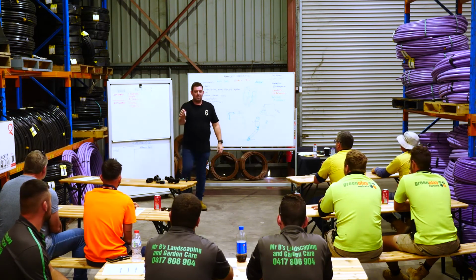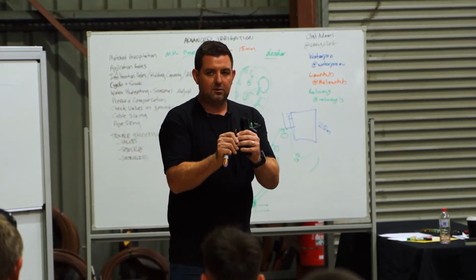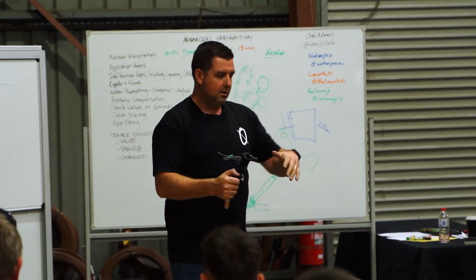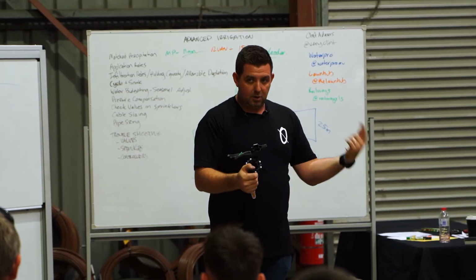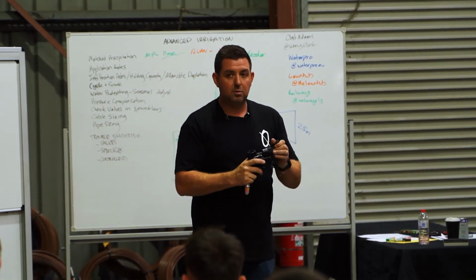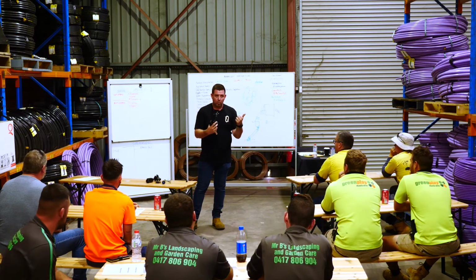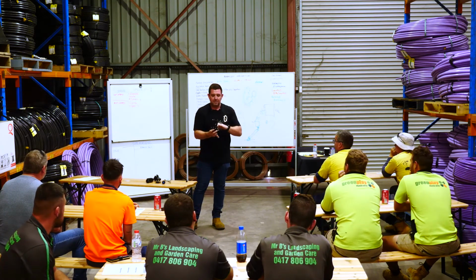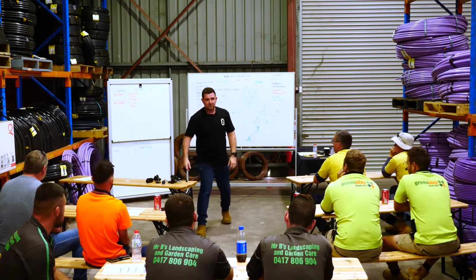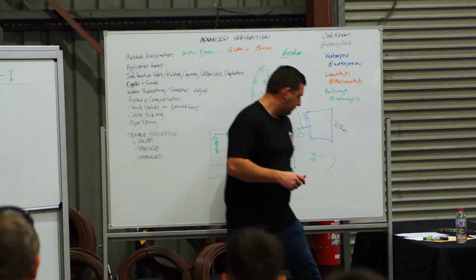The valve body itself in those situations, so a Hunter node has a standard Hunter solenoid valve with a different coil. A Rainbird DVF with a WPX has the same solenoid valve with a different coil. So all of the troubleshooting that you would do for the actual hydraulic side of it, so if there's not enough water or there's debris, is all the same. The electronics, or the electrics, is slightly different. And so it's just important for you to know the difference.